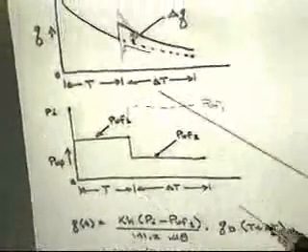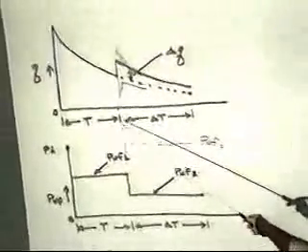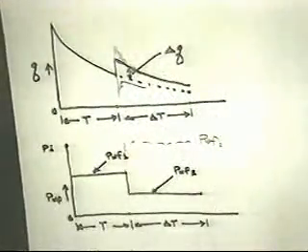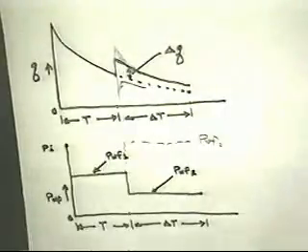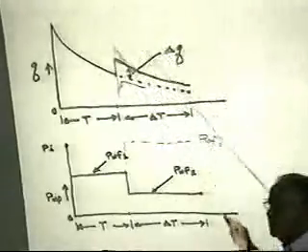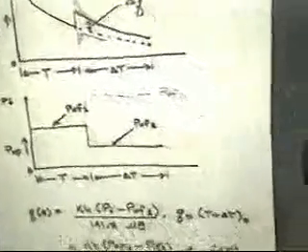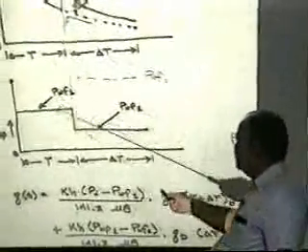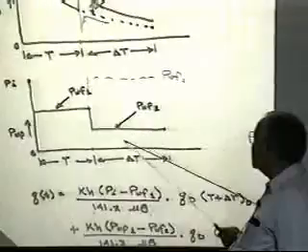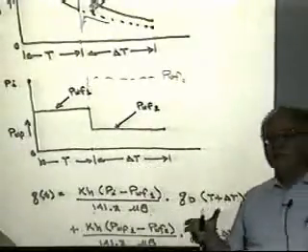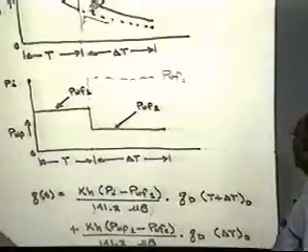The interesting thing is if you really look at data after a shut-in, you're going to get a transient spike. I know it's used here in the Ekofisk area. They've done calculations. Some people refer to that as a flush production or the ability to make up production because we were shut in. And you'll see the transient spikes when they bring the field back on after being shut in. Low permeability stimulated wells. The interesting thing is if you ever see a reduction in flowing pressure, the limiting case of reducing the flowing pressure is a shut-in.